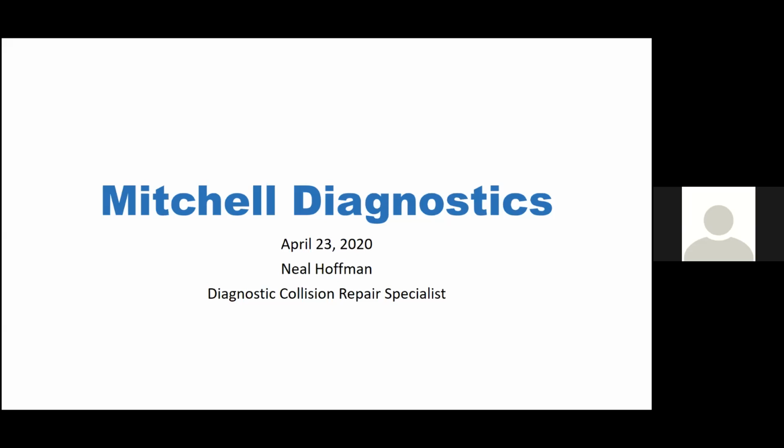I have my Mitchell Diagnostics slide up there, but this is going to be really general. Some of the topics we want to go over today are, number one, when do we perform the pre-scan; how to provide proper battery support when we're performing scans or calibrations; how to research fault codes; using a scan tool to reset, calibrate or initialize different sensors; when you should be performing your post-scan; and what to do when codes don't clear; and the importance of documenting these scans. Then we'll get into a little bit of dynamic calibration too. So I'll start with this.